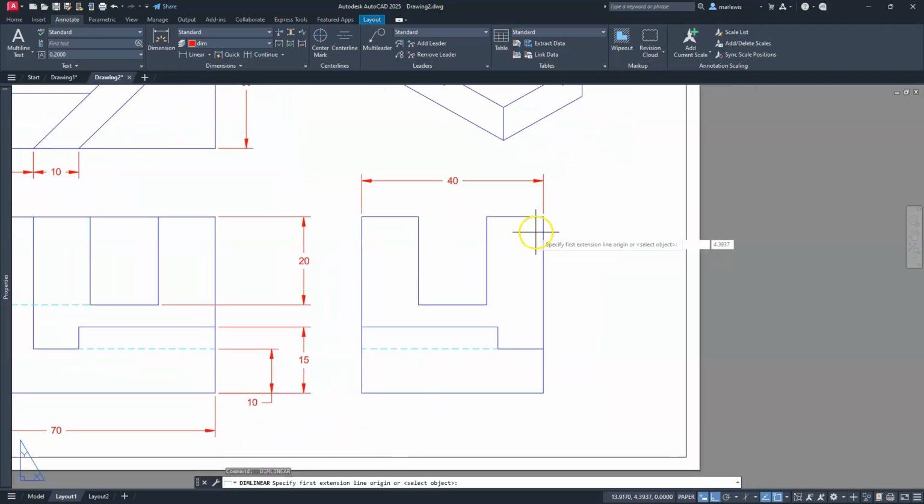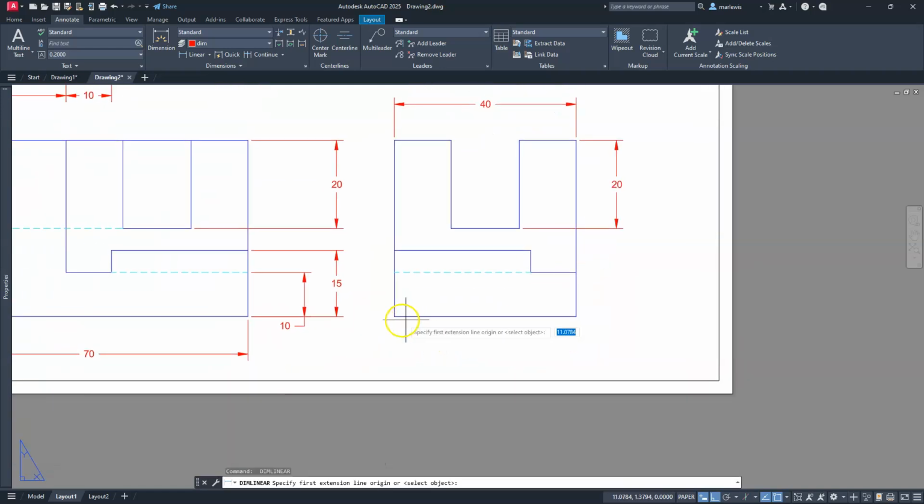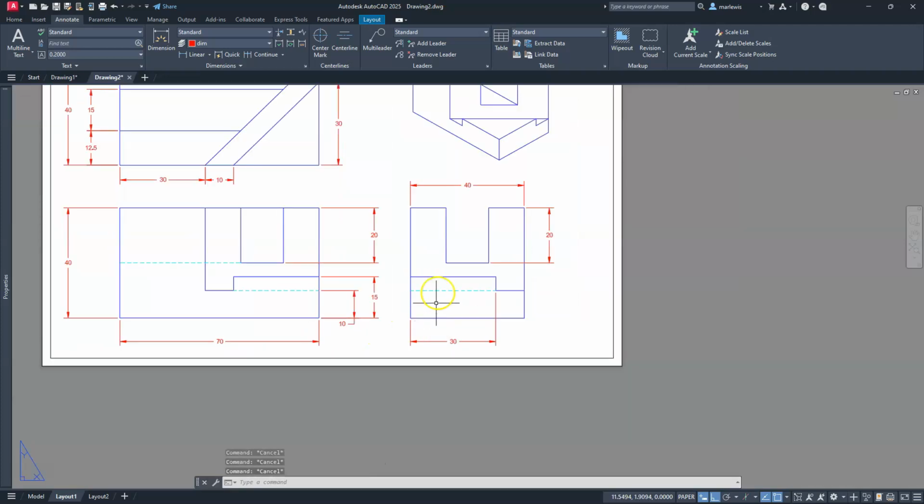It's just depending on what kind of space that you do have. So if you don't have the space for these extra views, by all means, go ahead and take off the view. But if you do have the extra space, make sure that you label these as reference dimensions. So whoever's building this, don't take that as a real dimension.